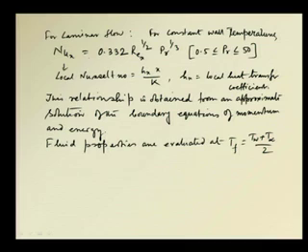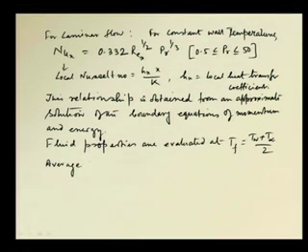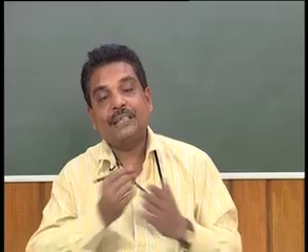So, from this expression whatever we have written, we will find out the values of local Nusselt number, and we will find out the values of h, the local heat transfer coefficient, if we have the ideas about all these other properties. Under that situation, if we try to know the average value, the average heat transfer coefficient is basically a value of heat transfer coefficient averaged over the entire length of the plate.